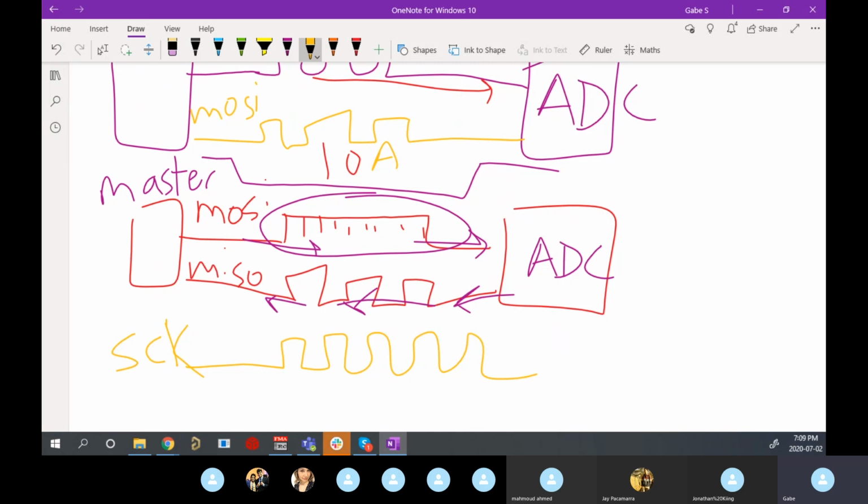Faster is harder because they need to sample fast enough to actually catch your clock rate. If you're toggling too fast and it can't handle it, it's just going to miss a lot of pulses, and so it'll get a bunch of garbage. But I'm sure there are some devices out there that beg for a specific frequency. I just haven't used any that are that precise. Do you have any, Junaid, in mind that you've dealt with before?